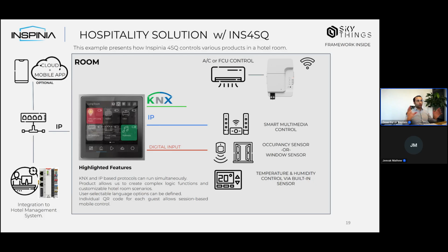to control all VRV indoor units. What is our limit, or is there any limit for VRV controls? I remembered, this is a critical point. For one port, for one add-on, except Mitsubishi Electric, other brands like Daikin, Samsung, Mitsubishi Heavy, or, for example, LG, Arçelik, support up to 64 indoor units. This is a protocol limit. It's not just our limit, but a protocol limit.